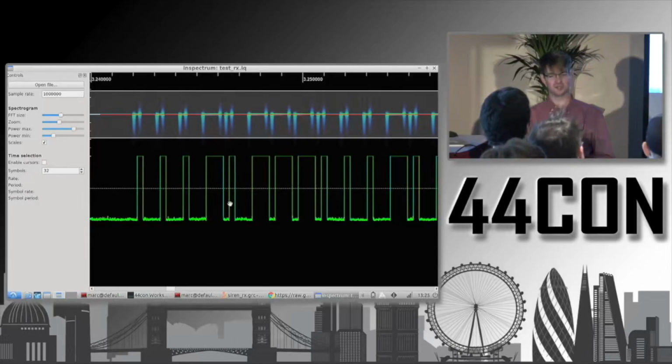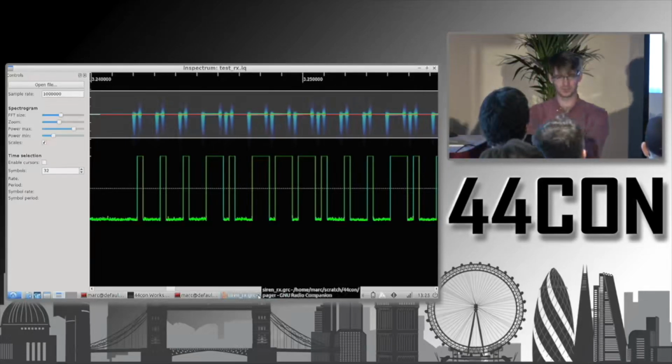So we can essentially implement some software, either by grepping through the file or in Python, looking for that sequence of bits, that sequence of symbol values, to denote the start of the packet. And then once we've found that, we can dump out the next, say, n number of symbols and use that to frame our packet. Is everybody good with that conceptually?